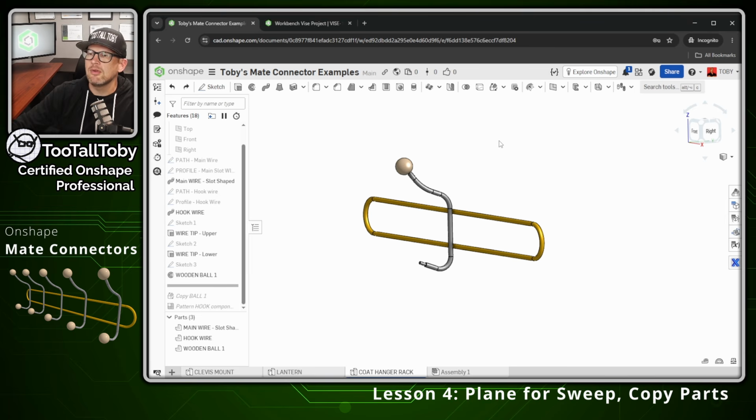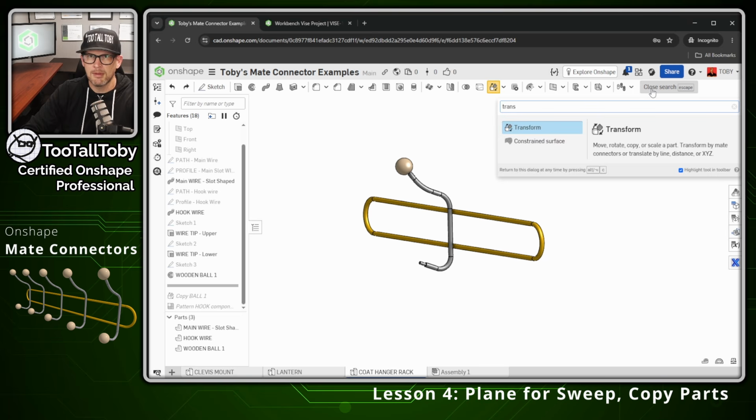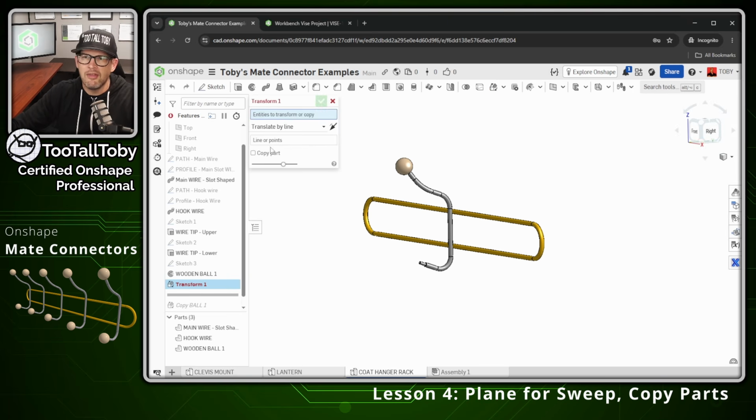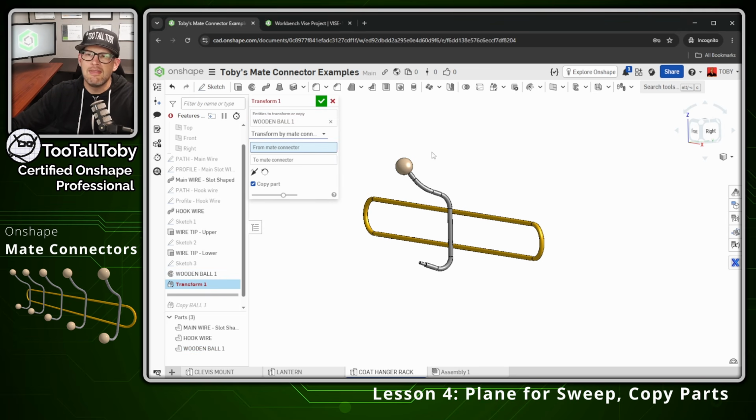However, you can also use a check mark within the transform command. So let me search for that transform command again. Enter, and there's a check mark here that lets you make a copy of this part into a new location. To define that new location, you could use translate by line or translate by XYZ, but you can also use transform by mate connectors. In this case, probably the best way to relocate this is to select the wooden ball here to be copied, and then hide the wooden ball down here at the bottom of the screen in the parts list.